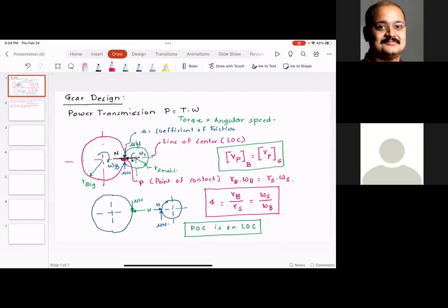We want to make sure that our transmission is forgiving to misalignment. So we are going to use the belt drives. On the other hand, if you look at Nissan, they say no, we don't want our customers to change the timing belt after 100,000 miles. So we are going to use chain drive. Once that chain drive is in place, it's continuously dipped in oil, so it will go forever. So those are different philosophies.